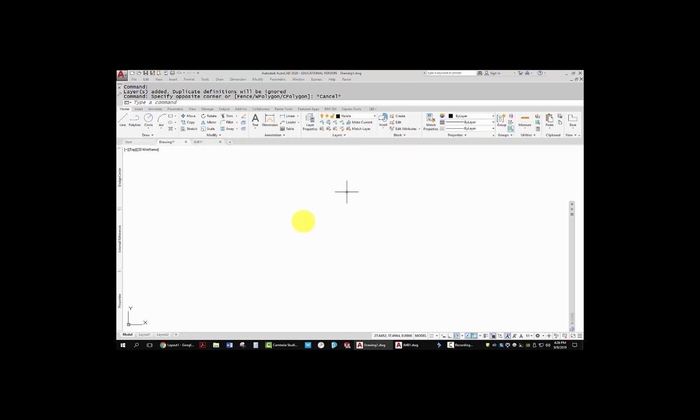I'm just going to pick a starting point of 0, 0, using a line command or the P-line command. L for line. Starting point 0, 0. I can type in as an absolute coordinate. I'm going to go down until I have polar tracking. Go 4 inches. I'll zoom in using my mouse. 2.5 is the height of this.